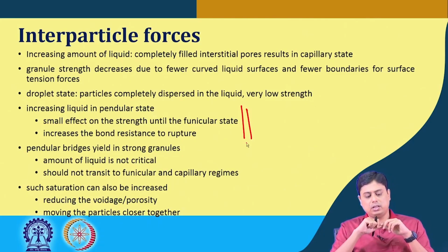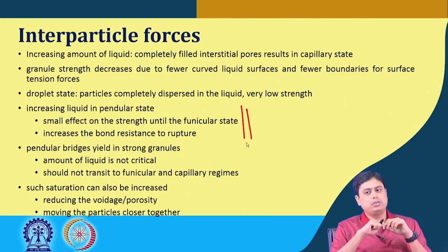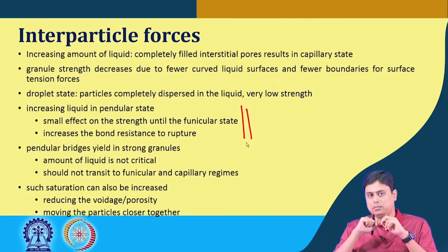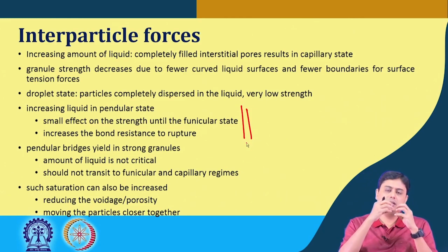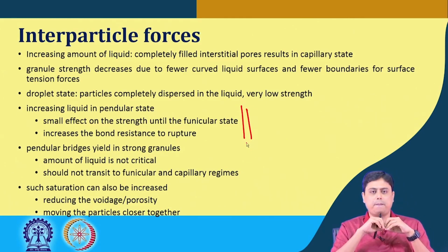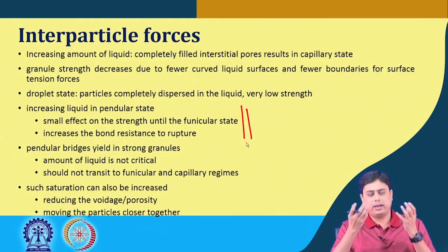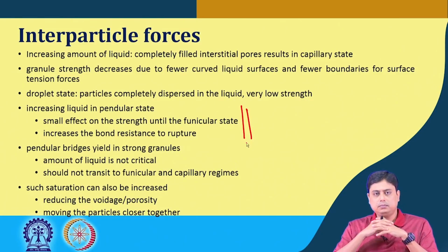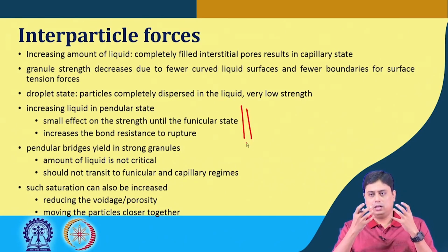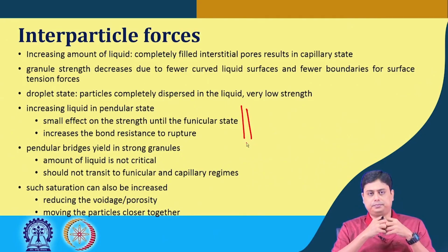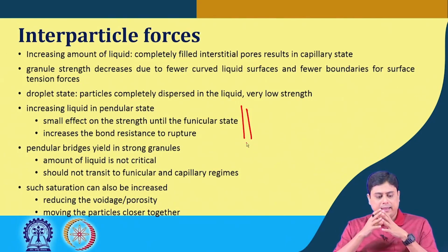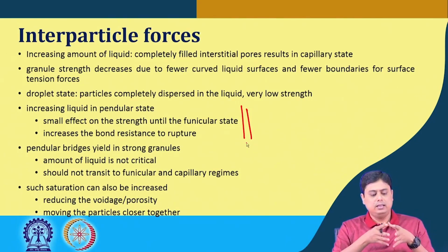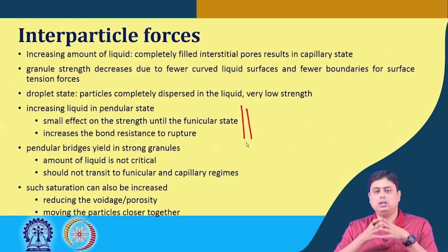Such saturation can also be increased by reducing the voidage or the porosity, or moving the particles closer together, which is called the densifying operation, or concentrating the particles together. And that is why we have seen these steps in terms of the forces that are acting for the liquid bridges.